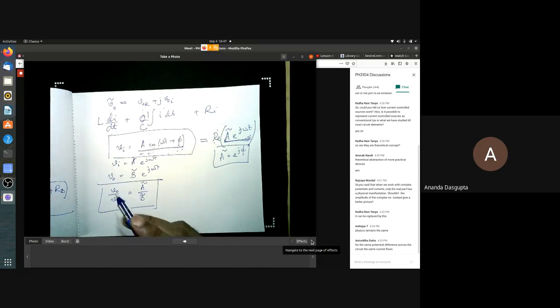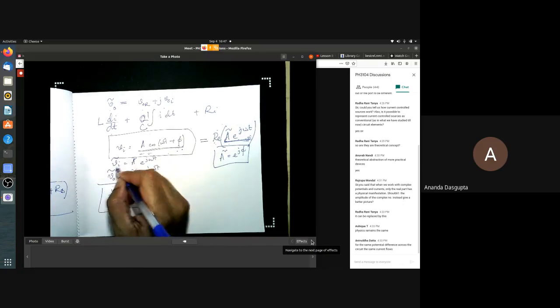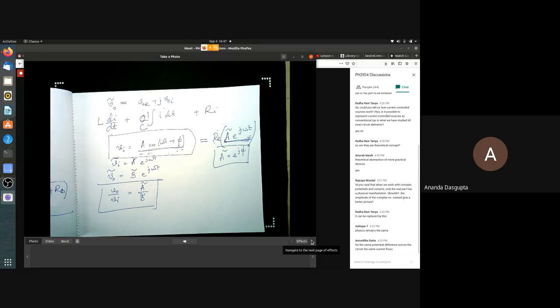This is actually not VI, this is VI tilde, this is VO tilde, the complex value representatives. However, because we often work with this, we don't say that these are the complex functions which represent the real functions. We just say VI is this, and happily calculate the whole thing. And then we realize that if this is r into e to the i theta, which of course is a complex number, then you can draw conclusions for the actual amplitude of the VO by VI ratio and the actual phase difference between VO and VI simply from here.